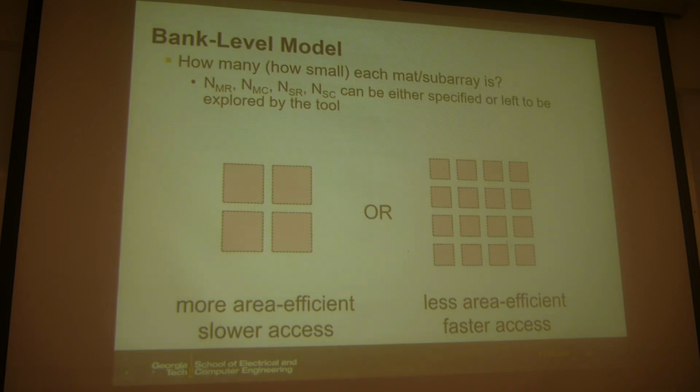This is exactly what you see in the SRAM cache. Let's say on the right hand side is an SRAM cache, and the left one maybe a DRAM, right? For the DRAM you can sacrifice the latency a little bit, but you care about the density and area efficiency, so you want to make this larger. Those are the design choices you may have to make.